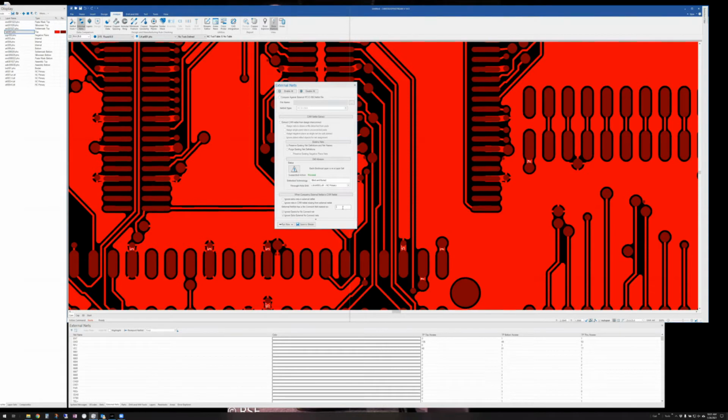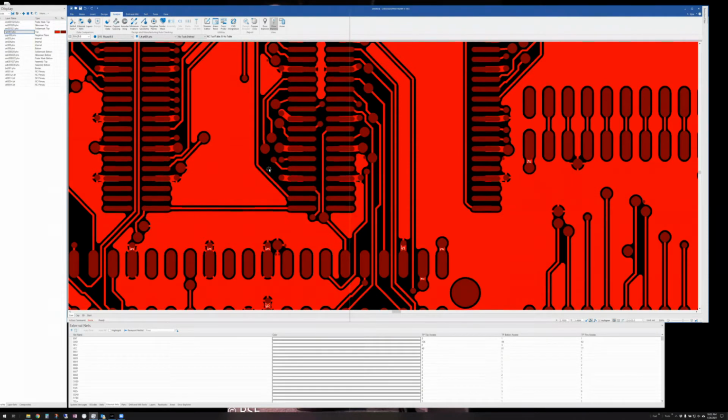Well, you can put that in here and it will ignore it when doing the comparison so that you don't get a lot of false opens for the nets that all have the same name but aren't connected. This is the way some CAD systems output it. But that's basically netlist comparison, which is the first kind of analysis and highly recommended. Again, my old board shop required it, by the way. You had to send a 356 netlist or you signed a release that we could not guarantee the quality of the design.